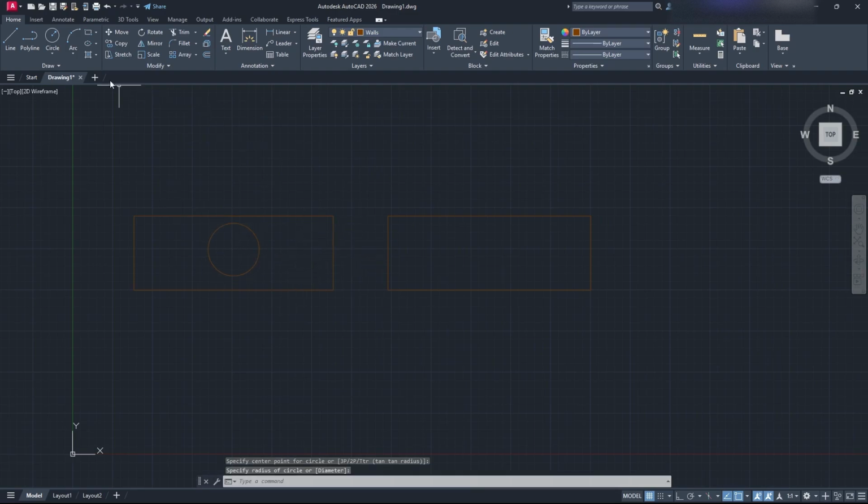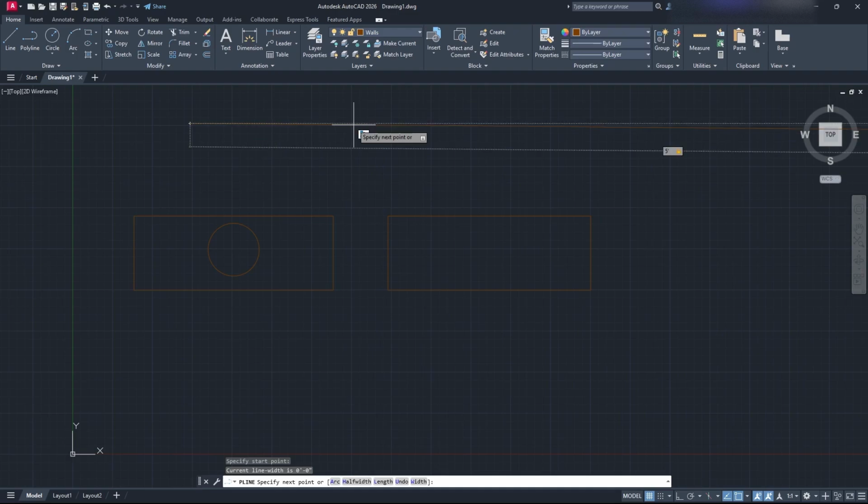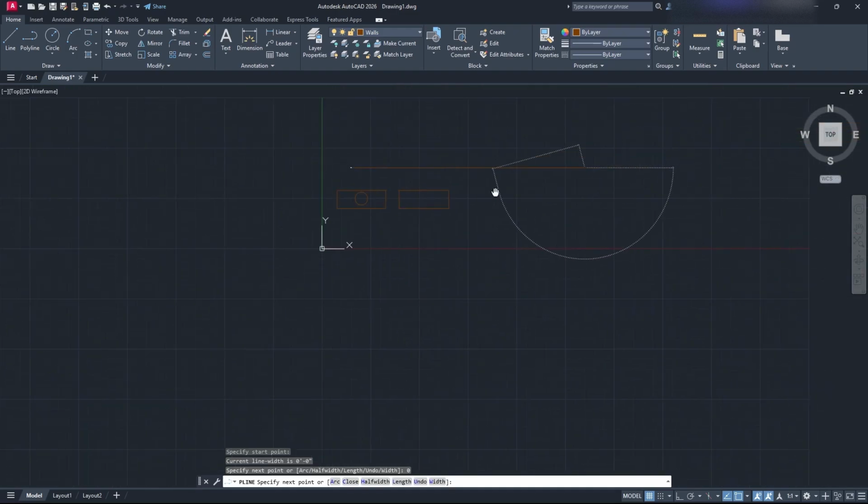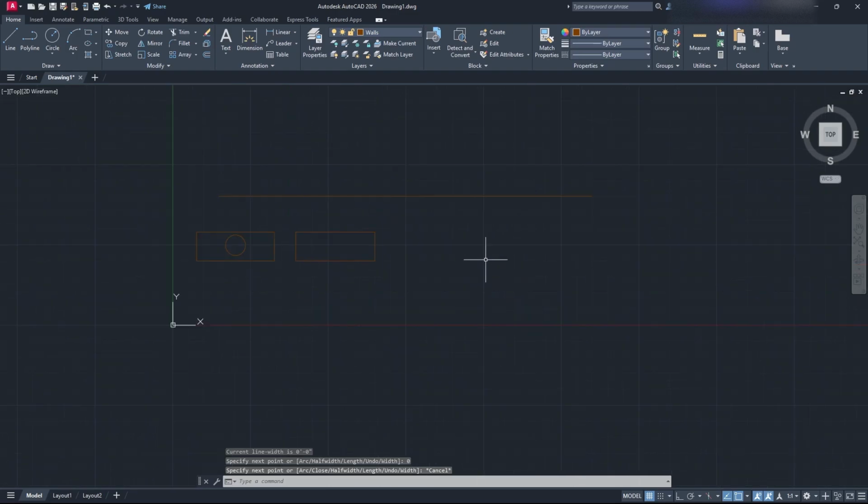And it's pretty straightforward. And you can see here when I'm drawing things, I have everything in my units. So this is a foot. So everything is proper in the way that I want it to be. I can also type in my lengths. So I don't actually have to select my line and pull it to where I want it and just mess around with it. If I know I want my line to be 5 feet, I literally type 5, put my foot there. And if I know what angle I want it, I just put 0, I press enter, and it's 5 feet. So you don't really have to mess around with that.